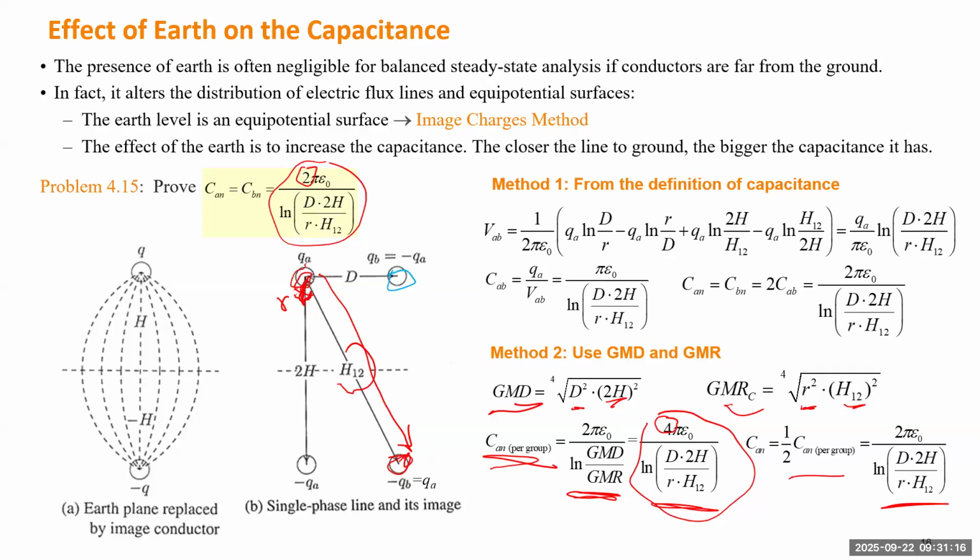And then they use this unit to energize first some transmission line, then pick up some load. So when they connect a transmission line to energize it, because they cannot add load to the line, they will connect to a line with no load. For such cases, the far end will create a very high voltage because most of the lines are underground, so they have a capacitance. So you can imagine when you connect a line, the line is connected to a capacitor. So the line may have an overvoltage problem.